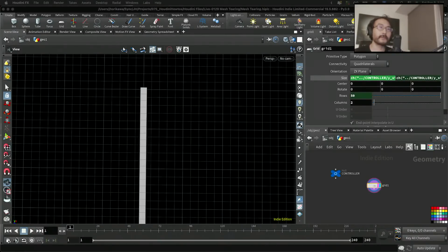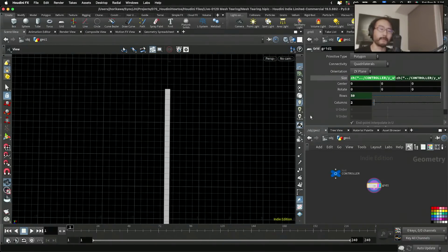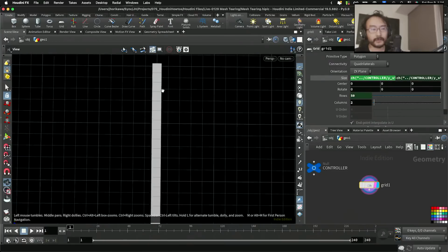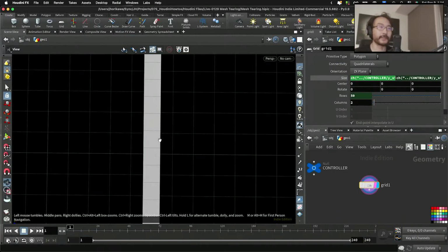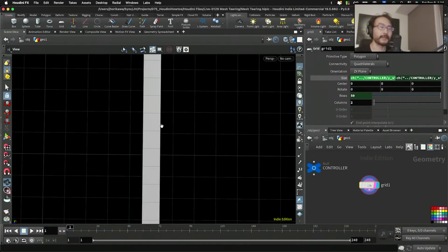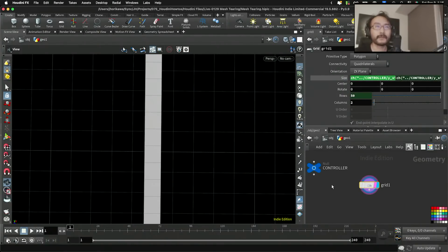Now what I want to do next is to create an initial wave, which is necessary in order to create a ladder vellum cloth. Because in order to create a hole or a cut for a vellum cloth, you need to make the initial mesh open. If it is stuck together, the vellum cloth node will see the meshes being connected to each other, so it's not going to make a hole on it. In order to make a hole or a cut with the lines or curves you're going to make for it, the initial mesh has to have some openings. Then later you can close it up after you have created the vellum constraints. But before making the vellum constraints, you need to have it opened.